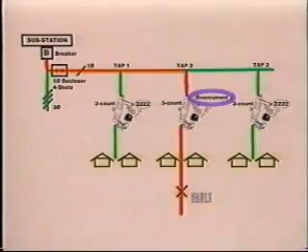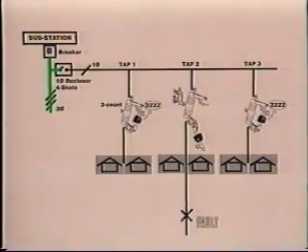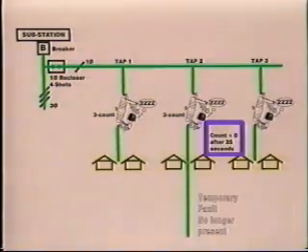When the recloser closes in for the 3rd time and the fault still exists, the sectionalizer will see the overcurrent, then the dead line. The internal counter will increment to 3. Since the device is a 3-count device, it will immediately operate while the recloser is open and isolate the faulted line. When the recloser closes back in, Tap 1 and Tap 3 return to normal line current, and a service call will be required to repair the permanent fault. If the fault was temporary, the sectionalizer will reset the count it has in its memory after 25 seconds.